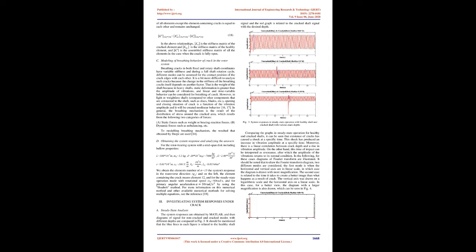For a disc of mass md and eccentricity e, relative to its center, the vector of force qd can be written as follows. It should be noted that in the following relations, α is the angle created by the torsional vibrations and Ω is the angular speed of the disc, so in these relationships Ωt plus α is the general angle of the period, as shown in the following figure. It should be noted that the above relationships are derived from the static equilibrium state, assuming that the reference is selected, so terms of forces caused by the weight of the disk have been ignored. Also in Equation 12, the displacement vector of the rotor system is defined for both sides of each element.